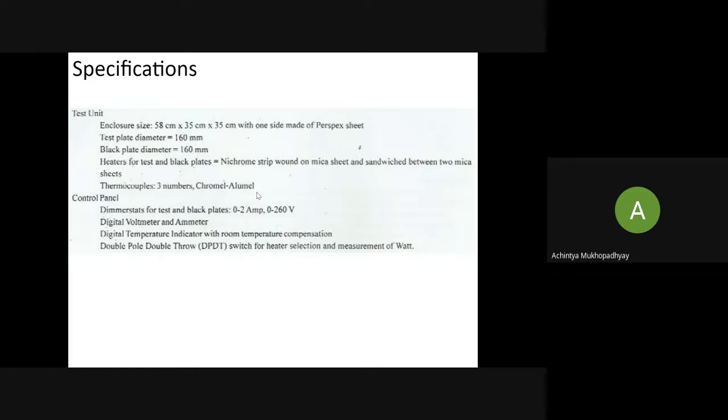And what is the opposite of the Seebeck effect? The Peltier effect. Yes. So there, if you maintain a voltage difference, that will create a temperature difference. So that is one way of cooling. That is called the thermoelectric effect, thermoelectric cooling. That is one way of doing refrigeration.